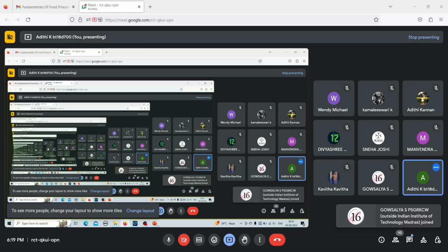So we are sending in steam to heat up the product. So the latent heat of vaporization of the steam is 2150 kilojoule per kg. If you remember, I said that there is generally no temperature change in the steam. There is only a phase change. So when you have a phase change, the latent heat of vaporization is the only thing that is differing between these two streams.